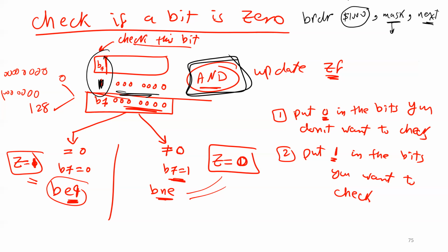So here, for example, if I want to check this bit, I'm gonna say here, look here, guys, 1 0 0 0. Then I can say 0 0 0. Is that okay? I can write it this way. So when I put it this way, I want to check this one. If you want to use branch if set or branch if clear, it's gonna be exactly the same way, because you just mark here, you just tell me which one. Is that okay? So what's going to happen here, this instruction is going to branch to next if this bit in this byte is clear. This one is going to branch if this bit is set. You got it?